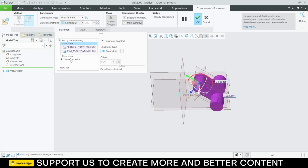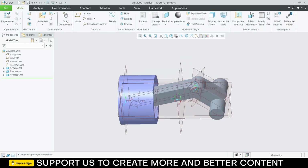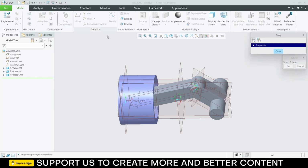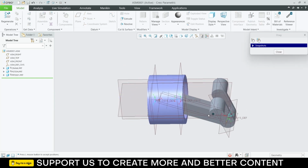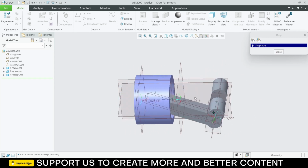Now the first thing that I have to do is click on new constraints. Select this and select this face. Here distance. Enter the value of distance as per your requirement. 150 is fine for me. Click OK. So if I try to drag right now, notice it is working quite well.